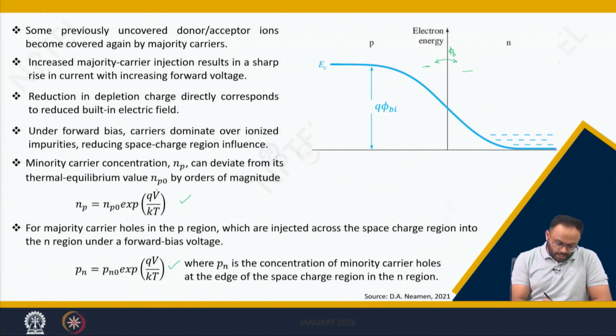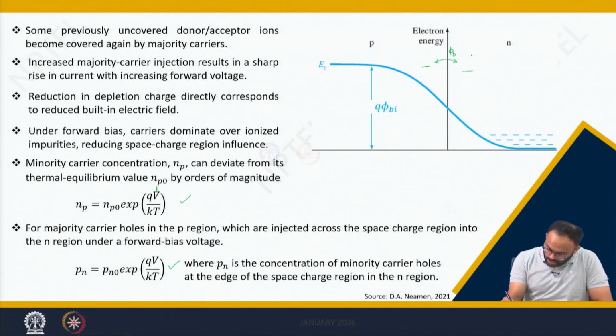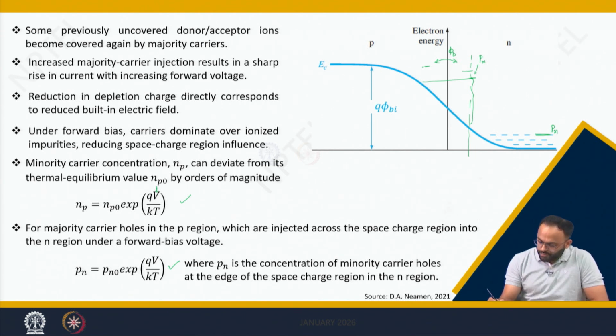Now whenever you apply a voltage V, excess charge carriers are generated in the p-n junction, and across the depletion region these holes will diffuse like this, and ultimately there will be excess carriers. So here at this side, this is Pn, and to differentiate this, we add Pn0, meaning the hole concentration at the n side under equilibrium.